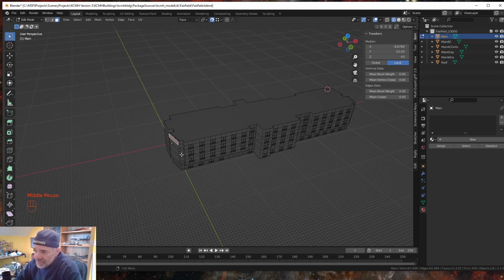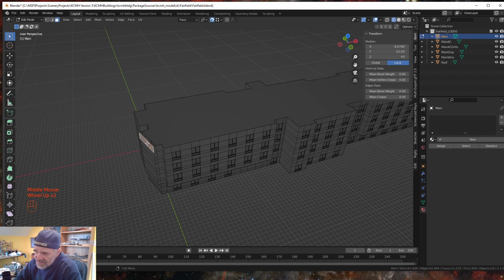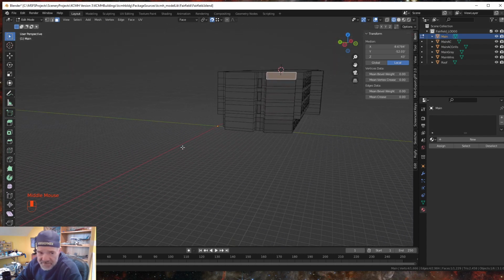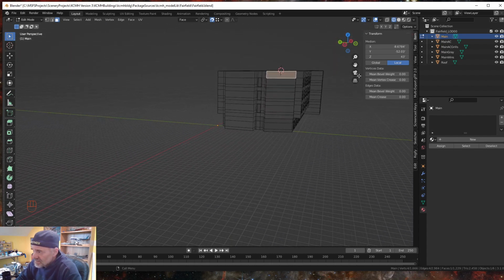But when you select a face like I just did here and create a new orientation, the XYZ changes. It's like you would be face onto that edge. So X is in this direction, Y is in this direction, and the Z is out towards you. So it's like you take that plane or that face and you lay it straight down on your worksheet, and that's the orientation of the face. You with me so far?